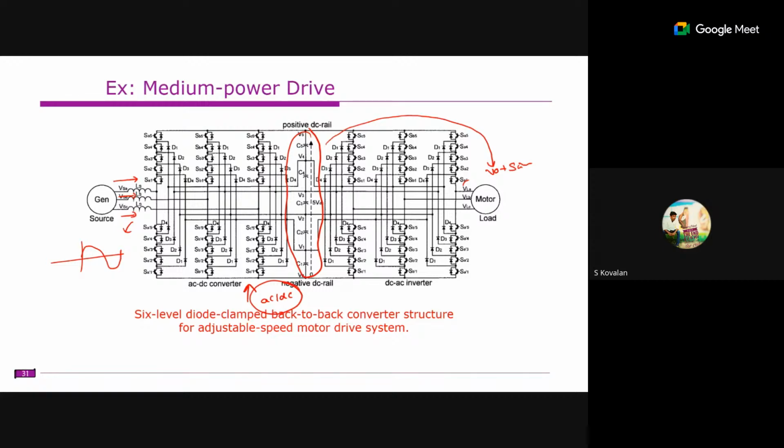But in between, because of the switching, harmonic current will flow from load to source. Whether power flows from here or here, the point is that this will be sinusoidal and this will be sinusoidal. The only thing is that the power flow is negative in that case. It will still be sinusoidal, but in opposite phase to the voltage. That means we can compensate the reactive power, operate at unity power factor, and at the same time keep it sinusoidal.